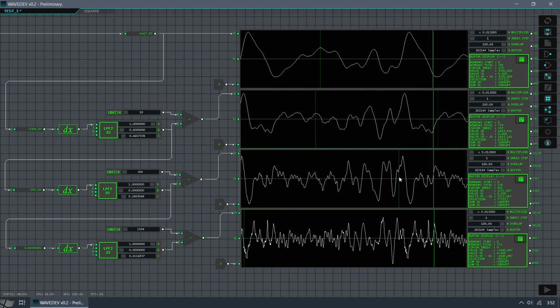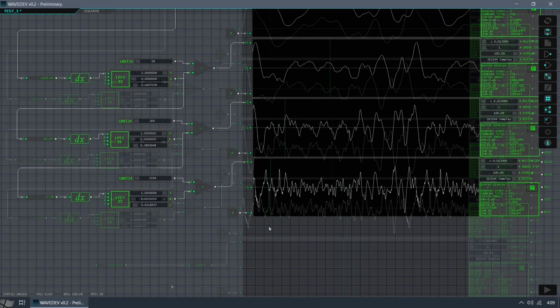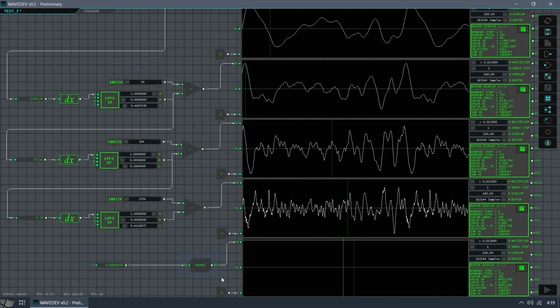Each filter increases the components that cross the zero axis. These are actually the components that the amplifier will saturate. Maybe it is not well appreciated in this way. So I am going to apply a function that simulates infinite gain. Our signal will become almost like a square wave. What is positive will be fixed to a positive constant, and what is negative to a negative constant.